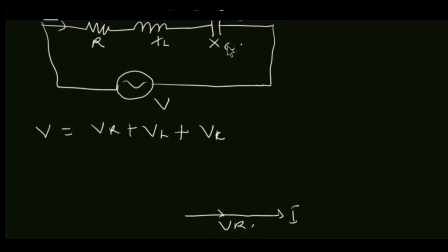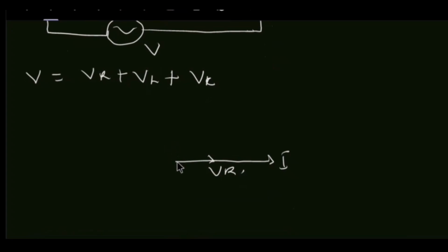Our XL and our XC rather have the voltage and the current not in the same phase. For that reason, our XL always takes the positive Y direction, whilst the XC takes the negative Y direction. This is because current in an RC circuit leads the voltage, whilst in the RL circuit it lags the voltage. So the voltage across the capacitor comes down. Here becomes our VC and here becomes our VL.